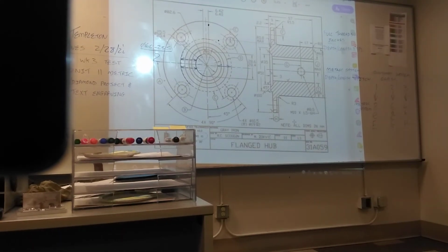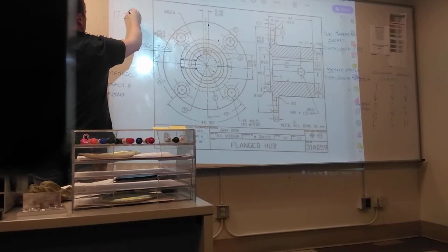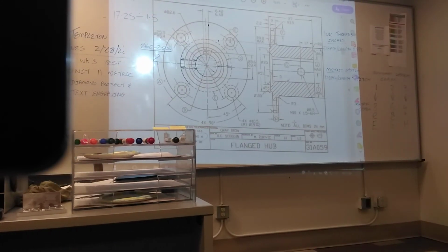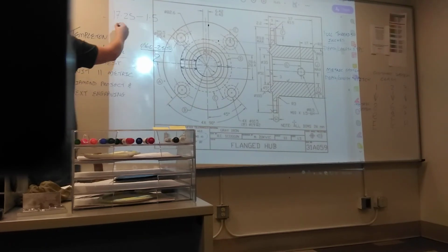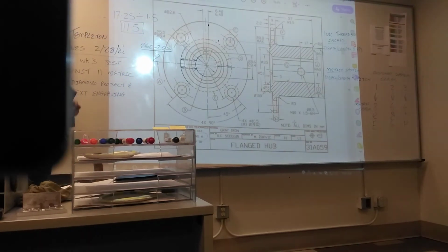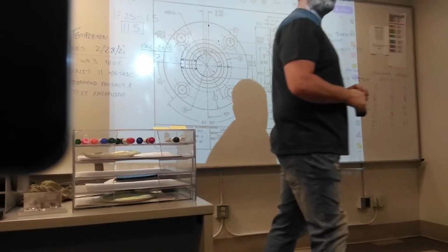60 minus 25.5 is 16. Divide that by 2. And divide by the pitch. What is the pitch? The distance from one thread to the next thread, which is 1.5. That gives us 11.5 threads. So how many full threads is that? 11 full threads.